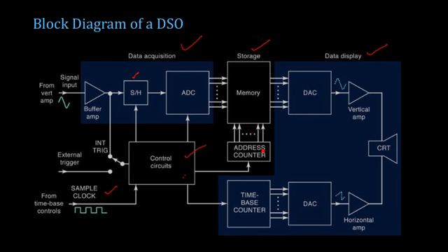And once the address counter is updated, the time-base counter also automatically moves. It will get adjusted in such a way that there is synchronization between the data in the vertical circuit and the time-base circuit, and you will be displaying the data in terms of dots. So you will get one dot, and that will be displayed on the screen.